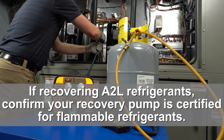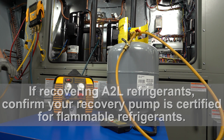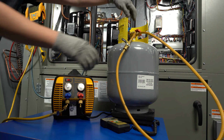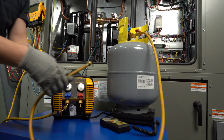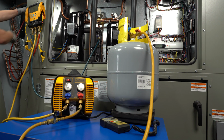The service hose connects to the recovery pump inlet port. Connect an additional hose between the recovery pump outlet port and the liquid port of a clean recovery cylinder. Starting at the unit, purge all lines to remove air.